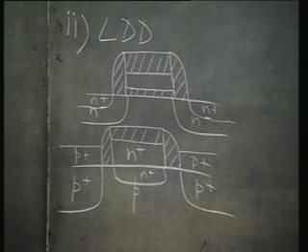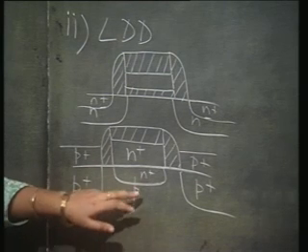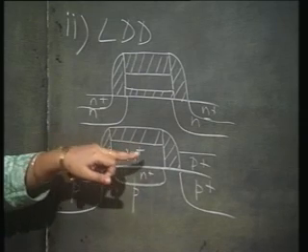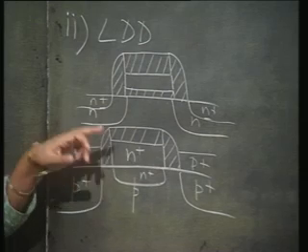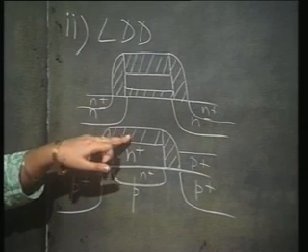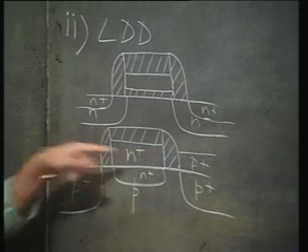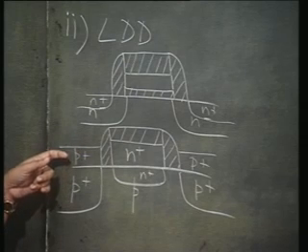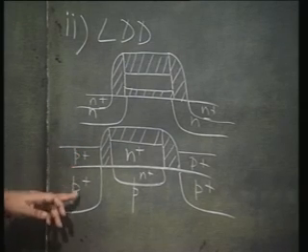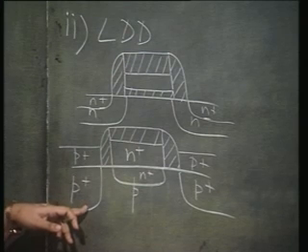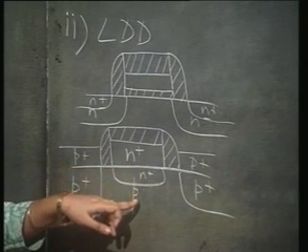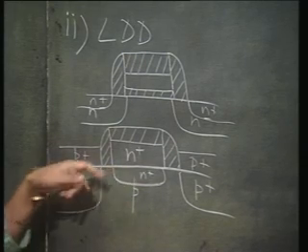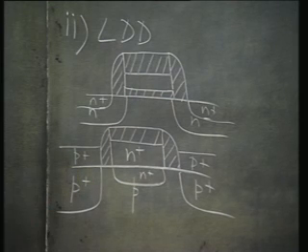So, in doing the same annealing step, what do we have here? We had the p type intrinsic base, on top of which we had deposited poly and implanted it with N plus. Then we had protected that poly with oxide on top and also oxides on the side. Then we had a poly deposited again and doped it P plus. So that after doing the annealing, from this P plus poly we had the P plus extrinsic base, from this N plus poly we had the N plus emitter, which was self aligned to each other, right. The N plus emitter was self aligned to the P plus extrinsic base.